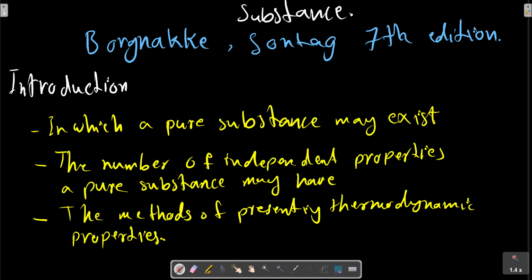Another example of a system where we need to know the properties of a substance is a gas turbine and a variation thereof, namely the jet engine. In this system, the working substance is gas and no phase change takes place. The combustion process burns fuel and air, freeing a large amount of energy, which heats the gas so that it expands. We need to know how hot the gas gets and how large the expansion is so that we can analyze the expansion process in the turbine and the exit nozzle of the jet engine.